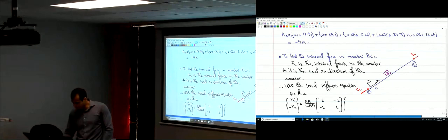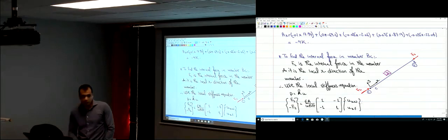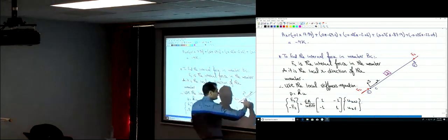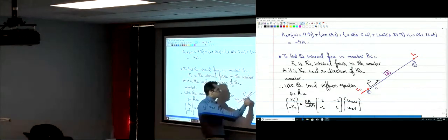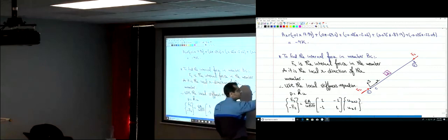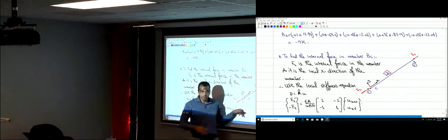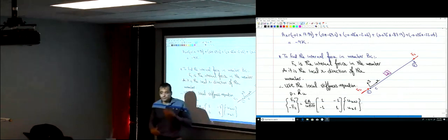What are the local displacements? u_x at the near end and u_x at the far end. Do you know how much those displacements are? The displacement at that node in the local direction, and the displacement at the other node in the local direction, not the global direction, not the global x and the global y.